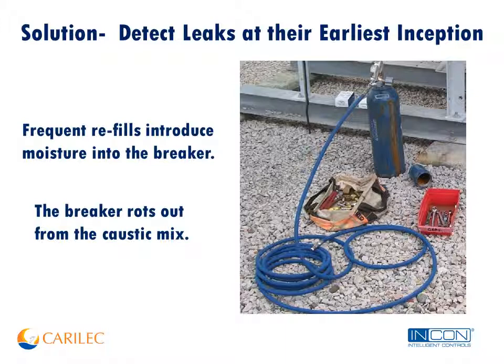Okay, detecting a leak is really more about finding the leak and repairing it than it is knowing when to refill it, because you really don't want to be refilling it all the time, especially in humid climates where moisture will ride into the breaker on hoses, connectors, and even the storage cases, the foam inserts that you put all these parts and pieces in, they hold moisture, and every time you refill with gas, you're sending more moisture into the breaker that really wants to be dry.